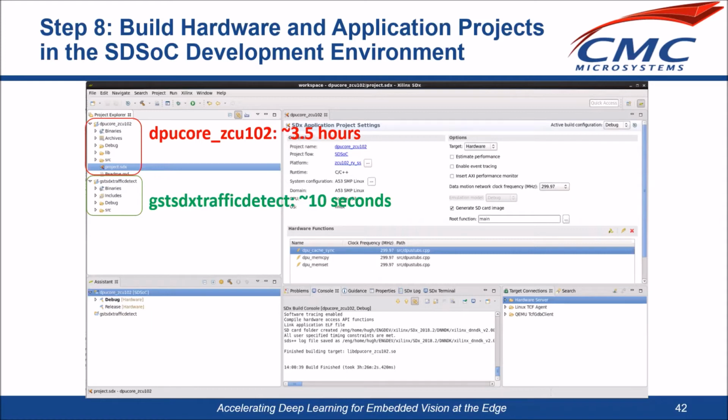So the first project is highlighted in red and generates the hardware. It's described in C, C++ and uses Xilinx high-level synthesis tools, or HLS tools, to automatically create the hardware. As you can see, it takes a considerable time to generate that hardware, 3.5 hours, depending on the workstation that you're using. But once you generate the hardware, you don't have to regenerate it every time.